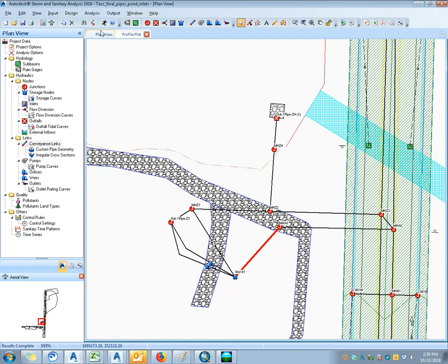I think that the pond doesn't rise as much with a single event. So you might have more flow coming in, but it's for a shorter time. I thought you were talking about your pond back-to-backs, not the single event. Yeah. This also, I didn't put any sort of overflow. I really should put in a weir or a structure that goes over to this point. You should. But it shouldn't be triggered. There's more modeling that needs to be done here.